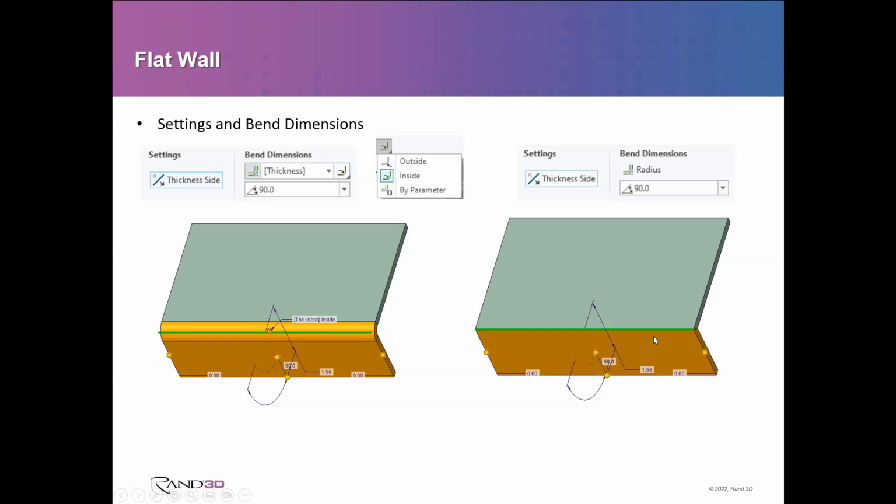You do need to have some type of radius in that corner to be able to unbend it, but you could come back and add it later if you wanted. But typically, you let the computer do it. And then again, if you are going to let the computer add the radius, then it's just a matter of specifying what you want that radius to be.